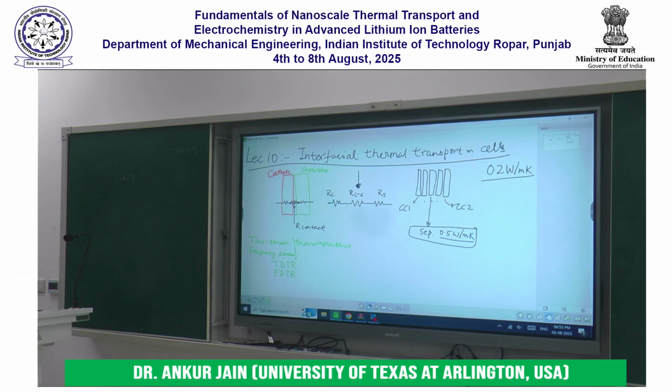No, we are talking about thermal resistances here, keep in mind. All of these resistances are thermal resistances. So in this course, unless I specify otherwise, resistance refers to thermal resistance. Remember that the thermal resistance of any body in one dimension is given by its thickness over its area and its thermal conductivity.